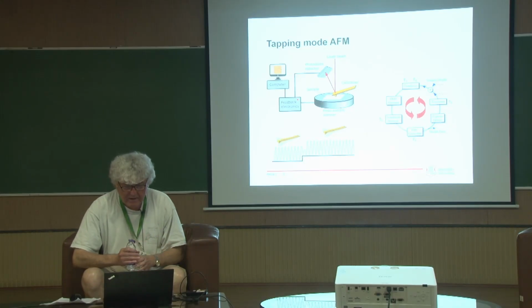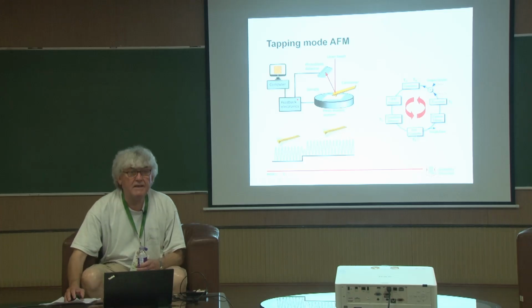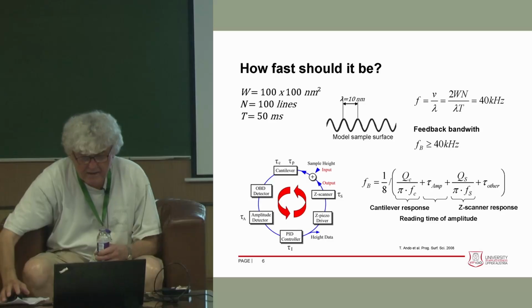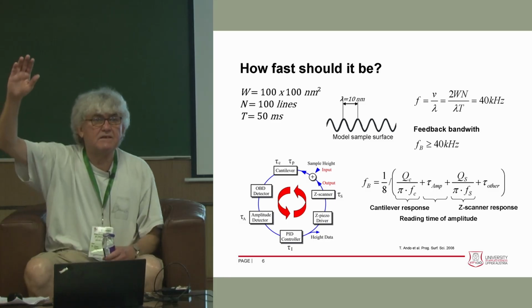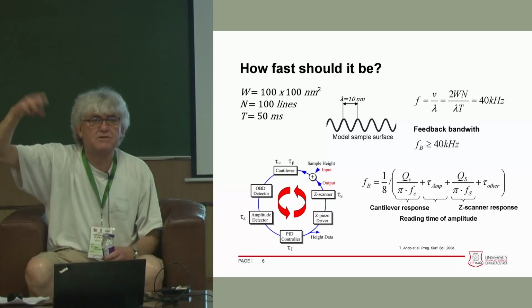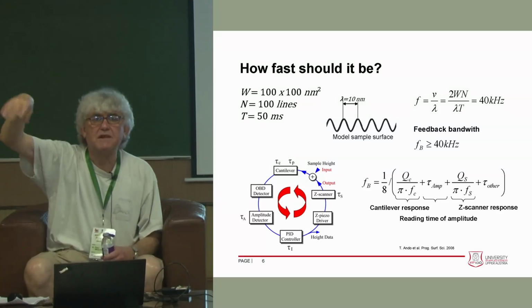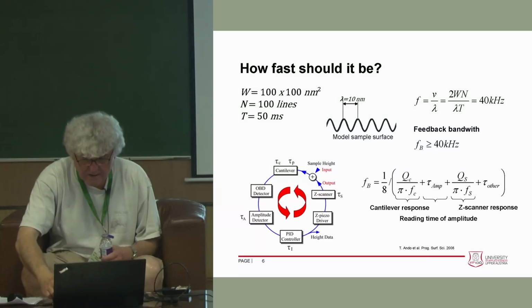Then you have to detect the amplitude, so there's the amplitude detector. The PID controller, which provides the feedback, so this also of course takes some time. Then a device that drives the piezo, and then also the scanner. So with each step of the analysis, it consumes a little bit of time, and there's some delay. And this is what has to be made fast.